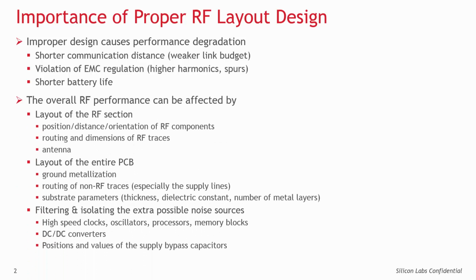At first, one would think that the RF performance is affected by only the layout of the RF section: the position, distance, and orientation of the RF components in the matching network, the routing and dimensions of the RF traces, and of course the used antenna. But beside these, there are a few additional factors such as ground metallization, the routing of non-RF traces, especially the supply lines, and even the substrate parameters: board thickness, dielectric constant, and the number of layers.